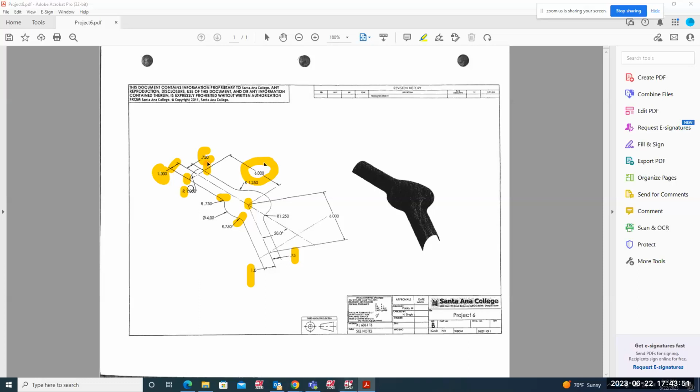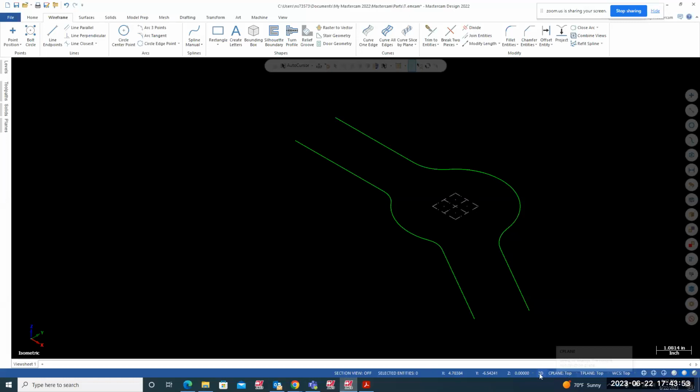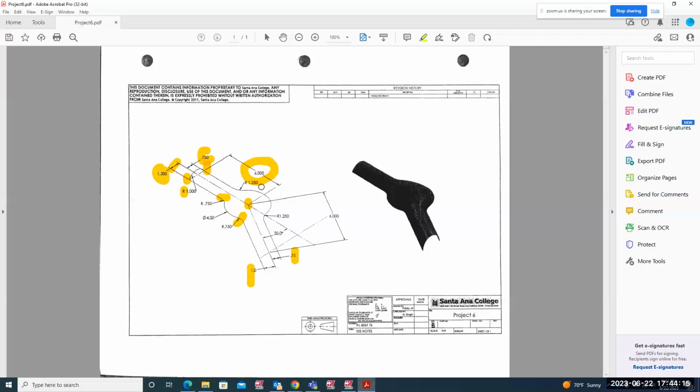So go to construction plane right, change to 2D. I'll go to construction plane right and click on Z. If you do, it says select point of new construction depth. Look at the Z minus 6 inches. You can see that on the blueprint also, it's minus 6 inches right there. So Z minus 6.